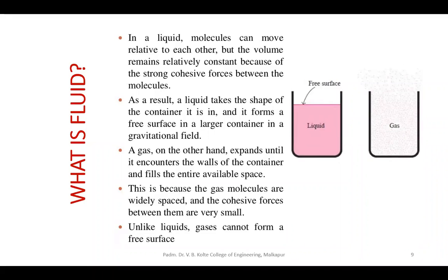What will gas do? It will not take a specific volume, it will try to occupy as much space as there is, possibly it will even cross the container, go outside the container, and no free surface will form. It fills the entire place available in the container. This is because the gas molecules are widely spaced and the cohesive forces between them are very small. Okay, first difference: the cohesive forces between the liquid molecules are strong, cohesive forces between the gas molecules are small. That will be the first difference between liquid and gas. Unlike the liquid, gases cannot form a free surface. Gas is not able to form the free surface above the layer of the gas.